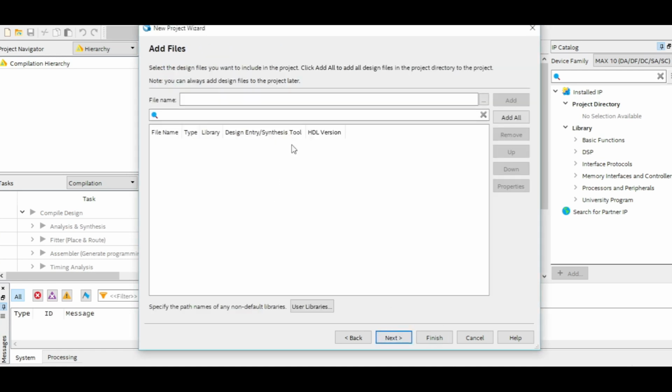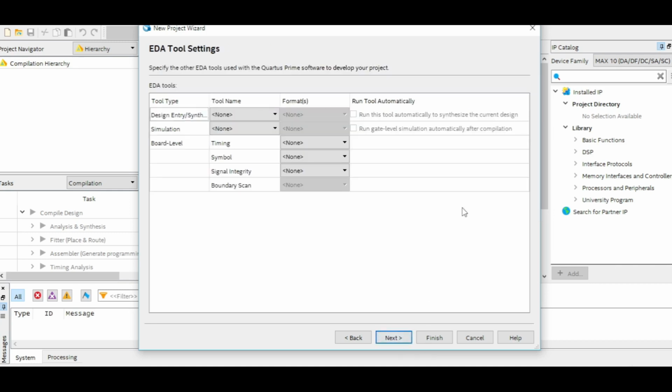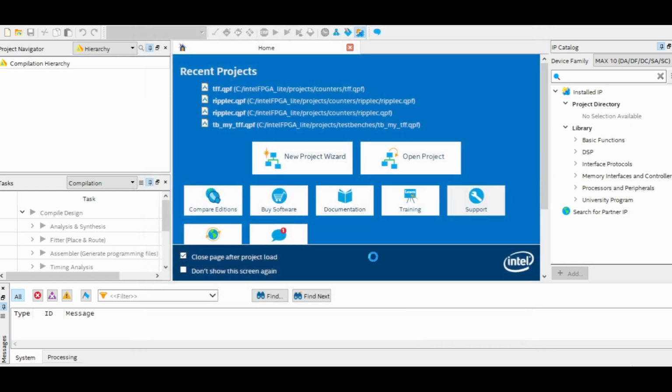It doesn't exist. Do I want to create it? Yes. Do I want to add anything in here? I could bring in my definition of the T flip-flop in here, I'm not sure we quite need it, so I'll just leave this for now, and if we decide to use it later on, then we'll bring it in. For now, 10M50DAF484C7G. That's the name of our device. And we have simulation as ModelSim-Altera, doing this in VHDL because we're going to have a test bench, so I'll go ahead and have this here.